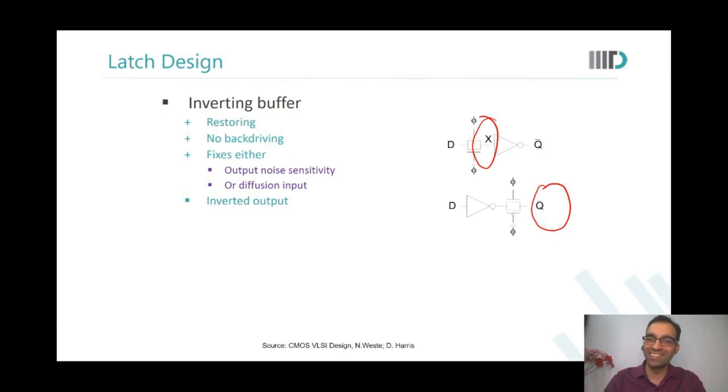Sir, why can't we use floating things? They are important to fix first. So therefore, we first talked about adding a tri-state. Sir, why can't we use the weak keeper over there, or a level restorer in between, to make sure that we won't float that node? That tri-state is what the feedback is, na, Vaishnav.